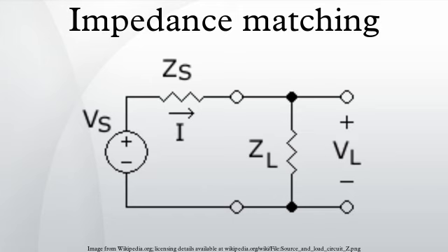If the wave encounters an open at the load end, positive voltage and negative current pulses are transmitted back toward the source. Thus, at each boundary there are 4 reflection coefficients. All 4 are the same, except that 2 are positive and 2 are negative. The voltage reflection coefficient and current reflection coefficient on the same side have opposite signs. Voltage reflection coefficients on opposite sides of the boundary have opposite signs.